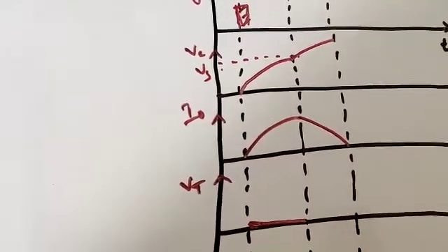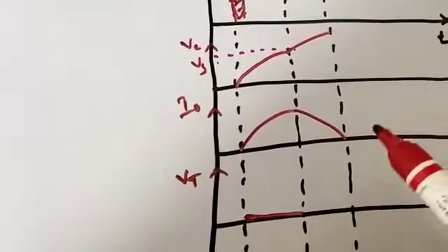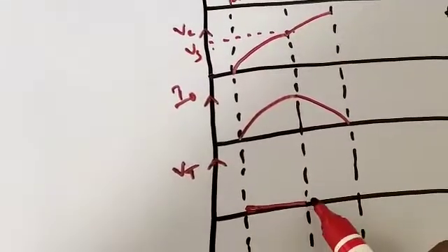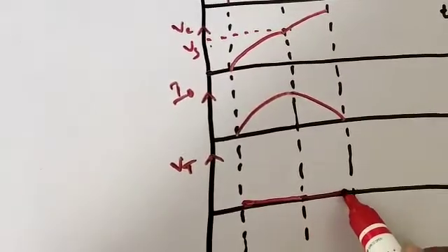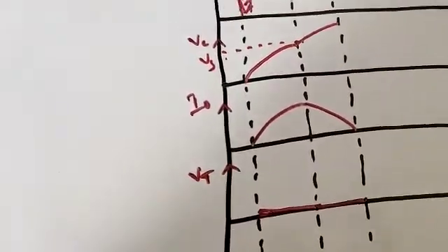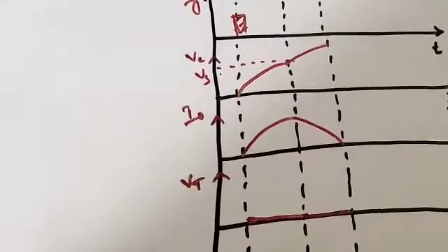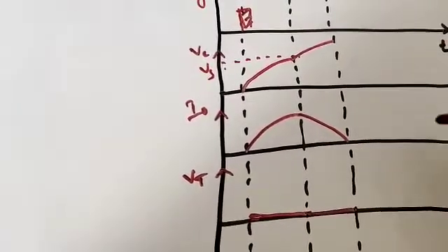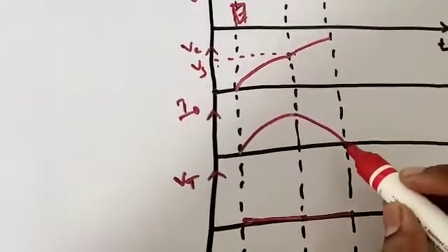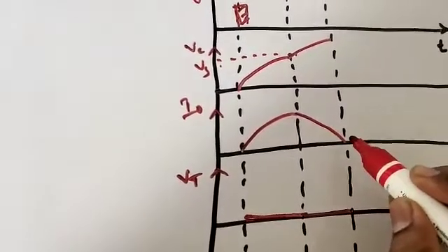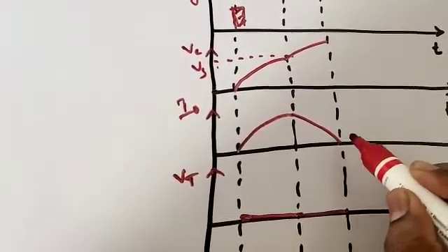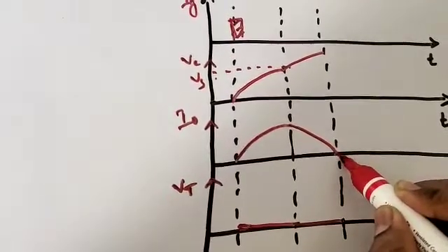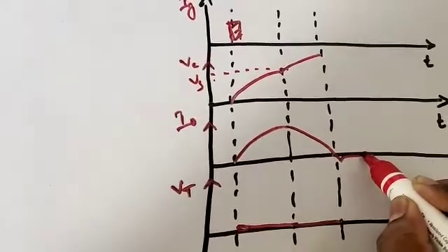Until it reaches 0, definitely the SCR is in on position. As the SCR is on, the voltage across the thyristor SCR will be 0 again. When the output current goes below the holding current, the SCR becomes off, like this.